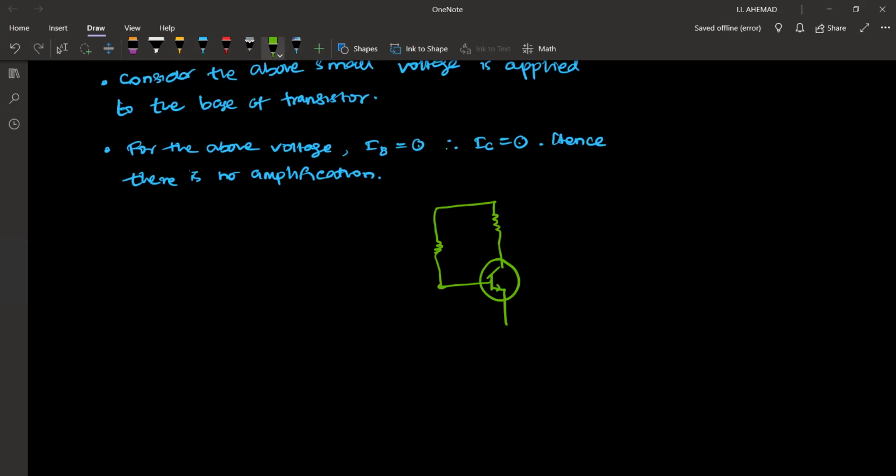So this is connected to plus VCC, and this is connected to VC, and this is earth. Now, by using a resistor RB, the base resistor, we already place this base voltage at 0.7 volts. So this is already biased. It allows current through it. Already the IB current is not zero because this is 0.7.